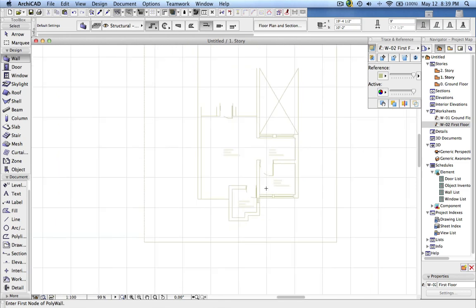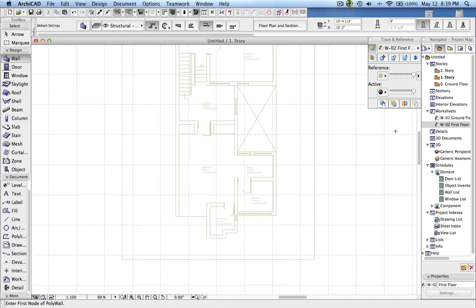So this is how you can use the drawing tool for importing the AutoCAD drawing, and you can use the trace reference. If you are using the drawing tool, as I mentioned, the whole drawing comes in as one drawing, and then you just have to crop the portion which you want to work on and put it on different sheets. Like the same drawing you will be copying and pasting on different sheets, and then just crop to the portion which you want to work on and align everything according to the ground floor, and then start using it as a reference as you navigate among multiple stories.